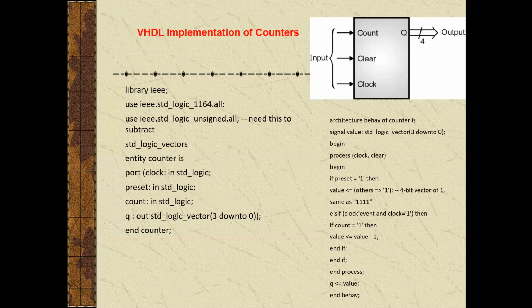Binary down counter. An n-bit binary counter can be constructed using modified n-bit registers, where the data input for the register comes from a decrementer or subtractor for a down counter, starting with the value stored in the register. To get to the next down count sequence, we simply have to subtract a 1 digit from it.